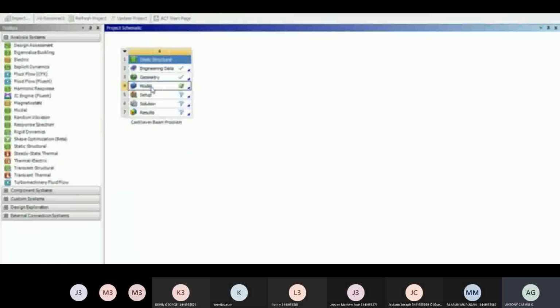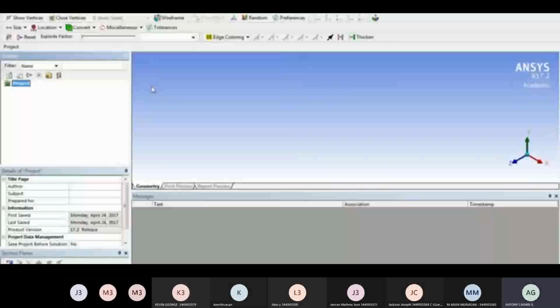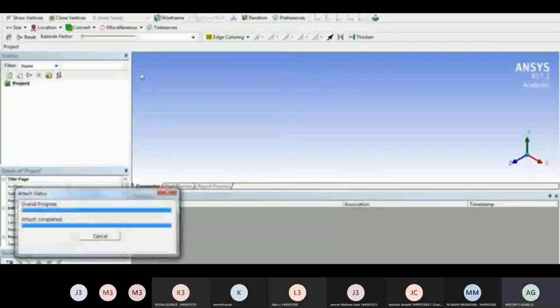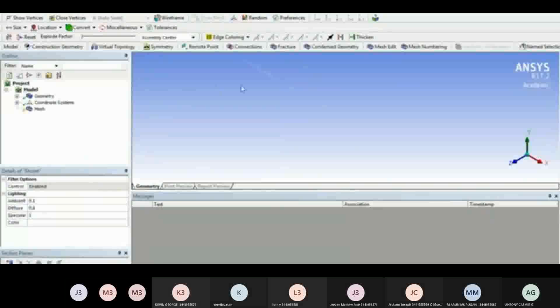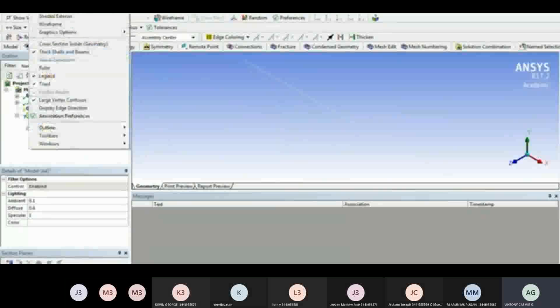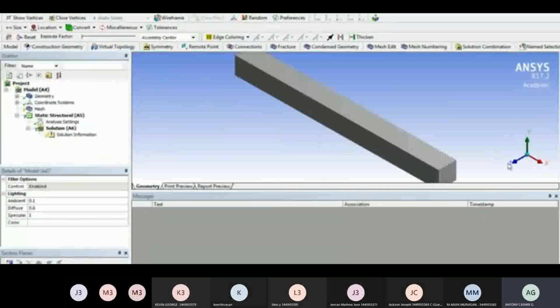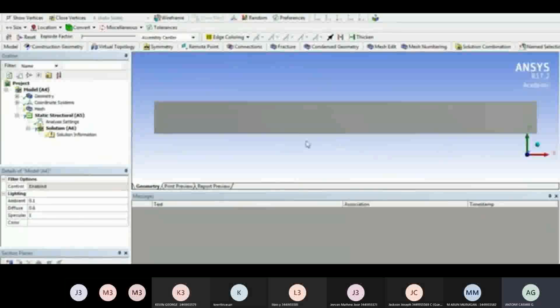In that model, we are going to mesh the element. Okay, is it clear? Mesh the element. Next, we are going to apply the project. We are going to select the mesh module. In that module, we are going to select the extrude option. See, the cantilever beam has been there. Next, we are going to select your geometry mesh. Okay, the meshing option has been there.